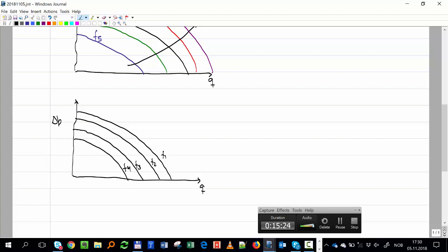First, there is a line that we call the best efficiency. That hydraulic efficiency I showed you before, there is a line, and the line usually goes through the center of the plot like that, and that's called BEL, or best efficiency line. And that's where the hydraulic efficiency is maximum.